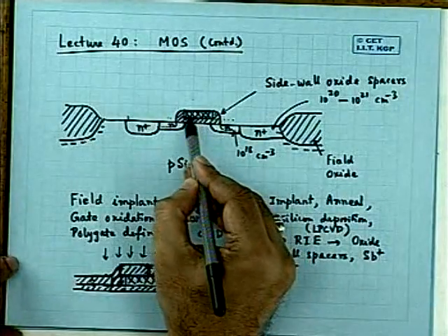You see that these sizes are extremely small. Films are extremely thin. So as a result, the sheet resistances of these films are relatively high. And then the line resistances are also very high. Very high means appreciably high, and that causes appreciable RC delay. To reduce the RC delay, what you do, we silicide the contact. You just deposit a titanium film everywhere.